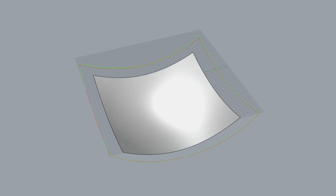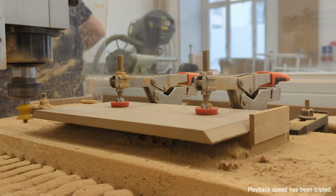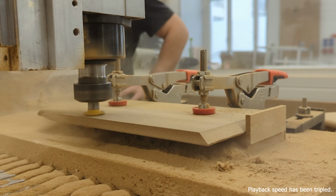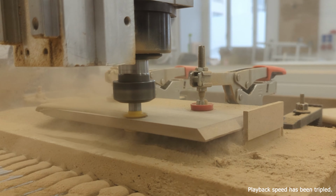We use physical simulation and optimization to improve the boundary curves and obtain a new set of curves, here in green. We use these curves to fabricate a membrane support frame. This frame is CNC cut from a thin board of engineered wood. Compared to machining the mold from a block of material, this is already a very efficient and cost-effective process. However, a fully reconfigurable mold can be constructed by replacing it with an adjustable support system.